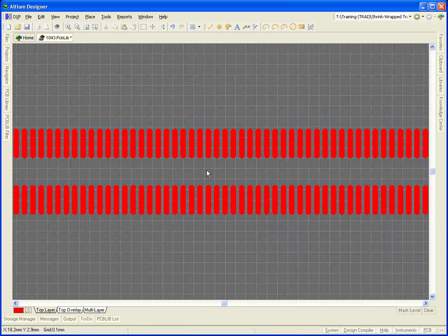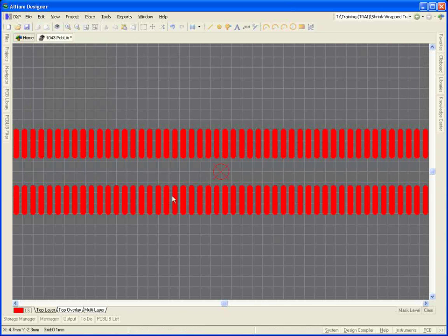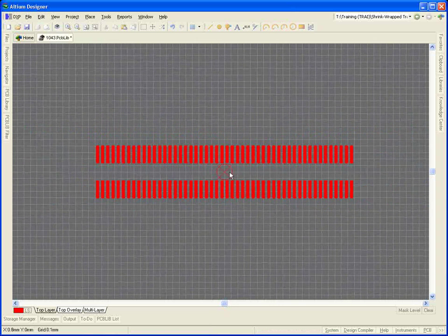OK, next it's time to place the mounting holes and overlay at each end. Since the dimensions are referenced from the geometric center of the component, you can set that as the reference point for your new footprint using the Center Menu command. Place the 2 mounting pads for the right-hand end first. Place, Pad, and then press Tab to configure the pad.